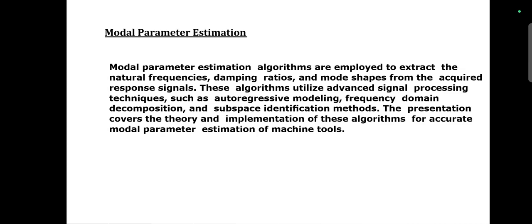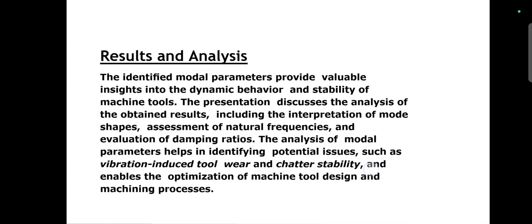Model parameter estimation. Now coming to model parameter estimation. Model parameter estimation algorithms are employed to extract the natural frequencies, damping ratios, and mode shapes from the acquired response signals. These algorithms utilize advanced signal processing techniques such as autoregressive modeling, frequency domain decomposition, and subspace identification methods. The presentation covers the theory and implementation of these algorithms for accurate model parameter estimation of the machine tool.